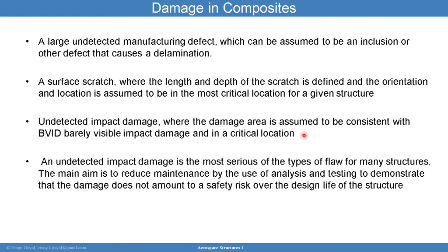The aim is really to reduce maintenance by using analysis and testing to demonstrate that the damage does not amount to a safety risk over the design life of the structure. Now, an aircraft exposed to environments for many years, 30 years, you can expect that at some point impact damage events will occur. And so that's looked at closely. Inspections are done over time by defining those inspection intervals. But most importantly, you have repair